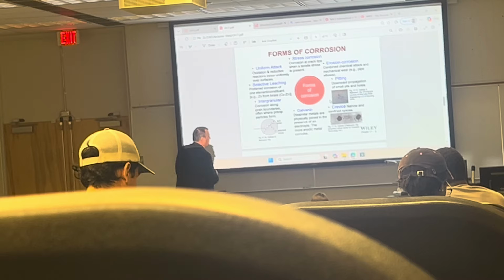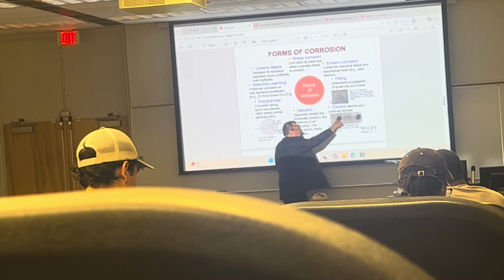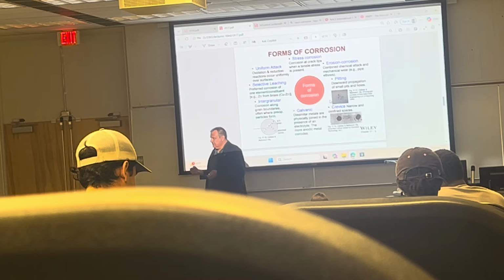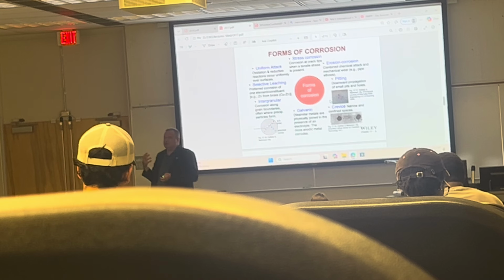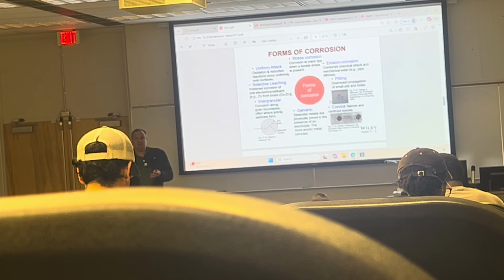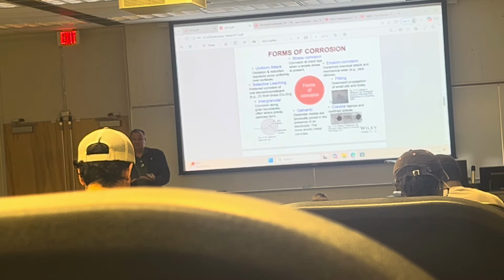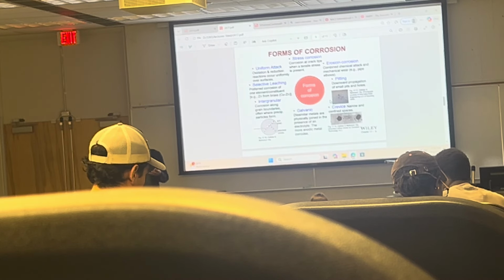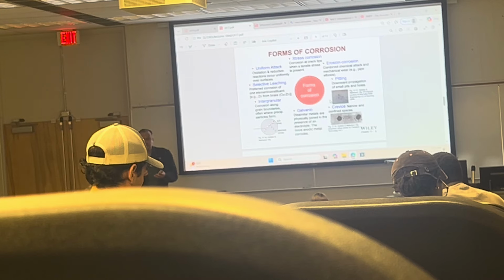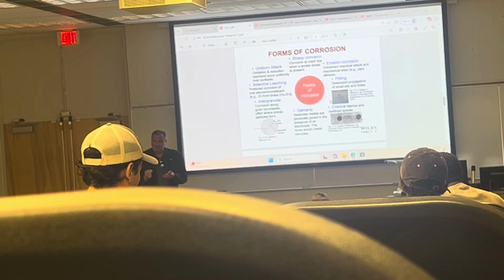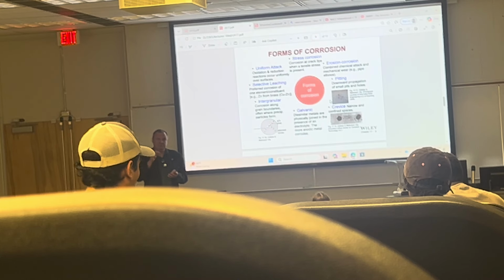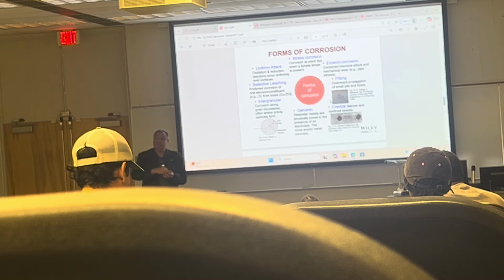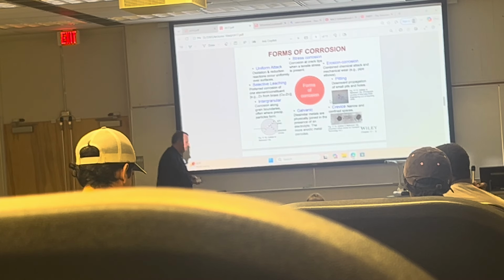There's also crevice corrosion, and these are rivet holes, and putting a washer or a rubber nut or anything like that creates anodic and cathodic regions. And what happens is this electrochemical attack is preferential. So at a very small area, it's all about per area. When the area is very small, the etching rate or the removal rate is very, very high, and the material just leaves.